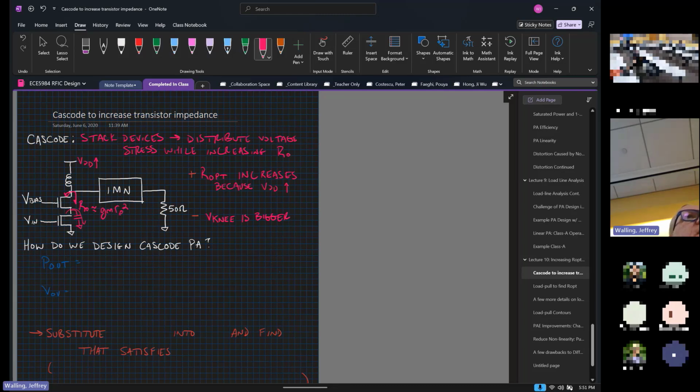That's something that's been done. It will inherently narrow band the circuit, but technically you could tune that capacitance out with an inductor. I don't generally think that it's worth it because the size of the inductor required to do that is typically quite big. And in fact, what is more commonly done instead of dealing with that capacitance, you've got the gate to drain capacitance due to overlap. So nowadays they just try and neutralize the gate to drain overlap and don't worry too much about whatever that parasitic is. Try and make it as small as possible by reducing the size of the cascoded device.